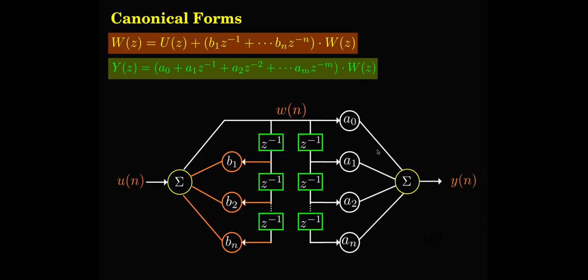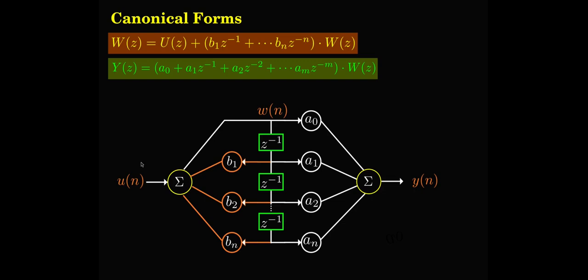So now all these, you will see that this is Wn and this is one delay, two delays, and so on. All delays of the same variable Wn. So these two can be merged together. So I'll merge them. And this would be the optimized standardized form of an IIR filter, a generic IIR filter. This is called the control canonical form.